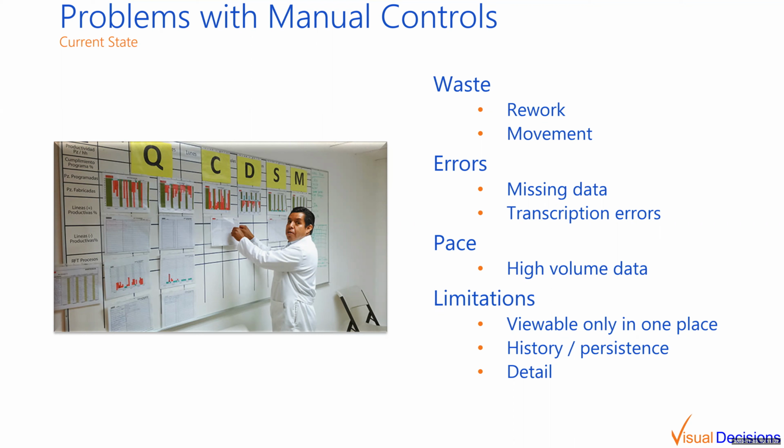And that was driven by a lot of short stops, minor stops, jams, et cetera, on the equipment. And sure, they were short, but they added up over time. And the current approach was capturing less than 20% of the total downtime as well. Everyone meant well when they were doing the data collection, but when the machine only stopped for 60 or 90 seconds for a jam, nobody bothered to write that kind of event down. It's just the way that the line worked. So when they went to improve the performance through Kaizen events, they were using information that was just woefully incomplete. They didn't even know what the big problems were, let alone the root causes of performance.